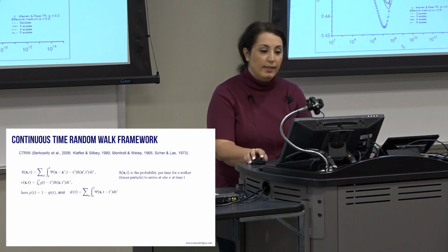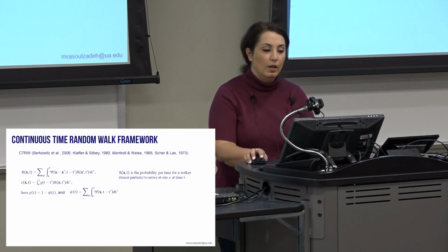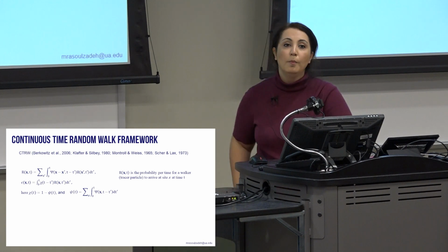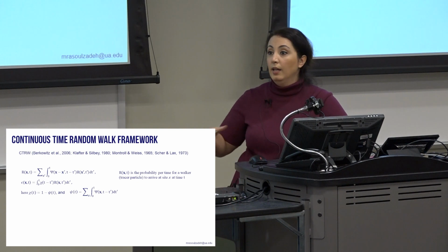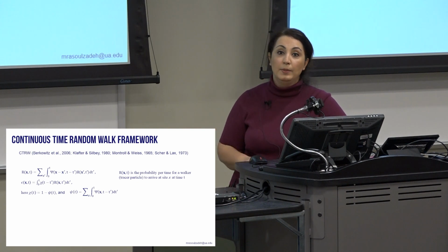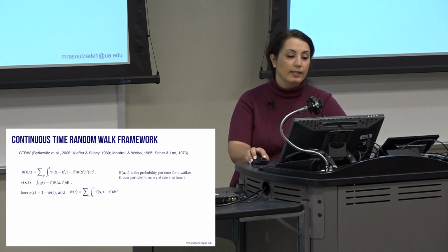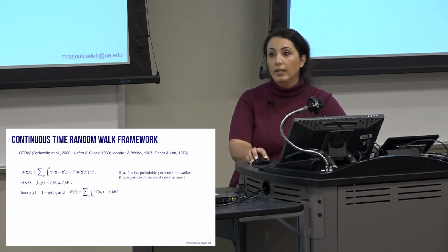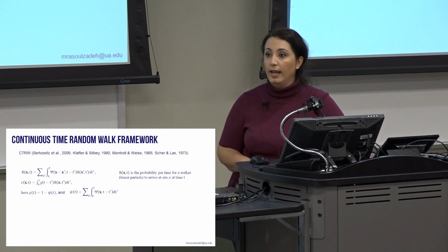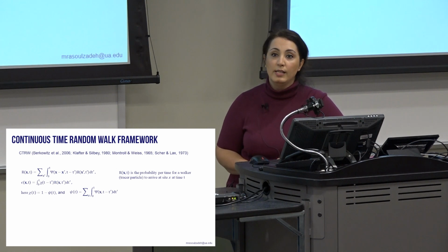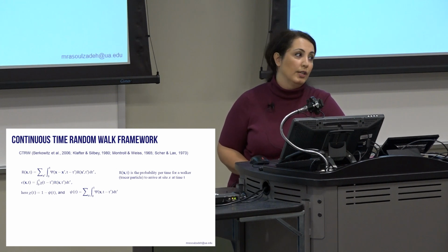So if I say that I have the flow model somehow in place, I would prefer to use the flow model that I obtained by two-scale asymptotic approach. And using that, how can I approach the transport problem? Given that I just gave a transport problem a try and I couldn't go until the end of simulation for that very simple case that I have. What if I want to look into the transport problem in a naturally fractured reservoir?